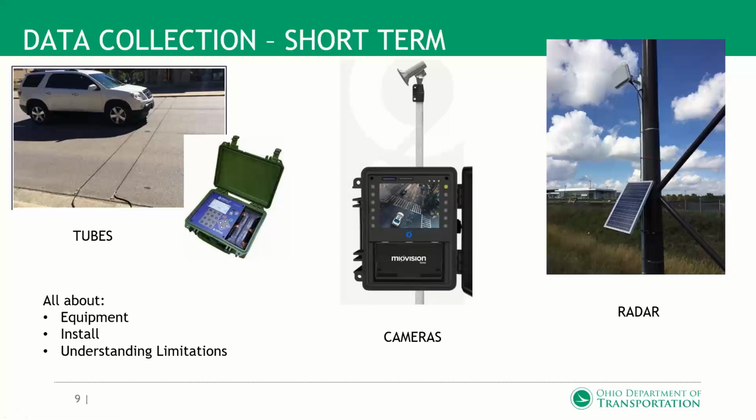I would not trust their classification, especially do not trust it in an urban environment, which is a lot of times where these are used because you don't want to be in the road with the tubes. But you're not in the road, and if you install them correctly at the right distances, you can get really accurate volume counts. We have about 70 of these set up permanently, and there's only 3 of them that we trust the classification data on.